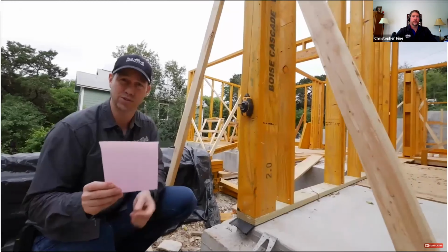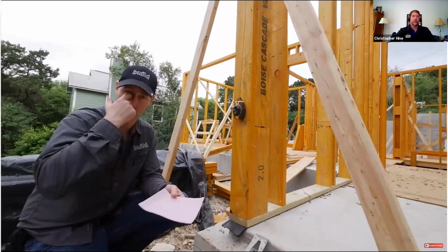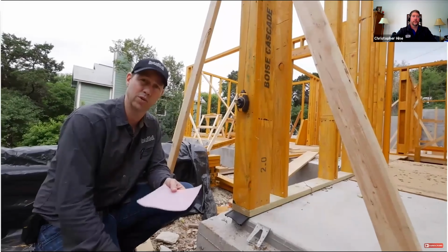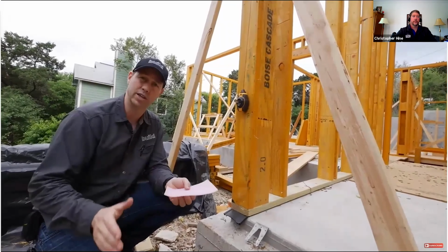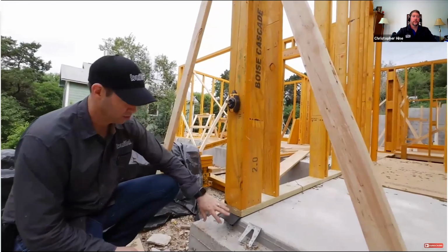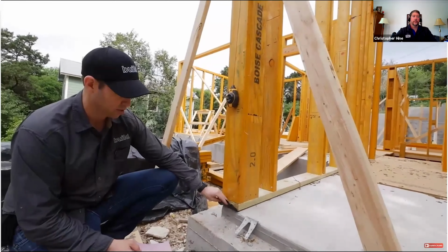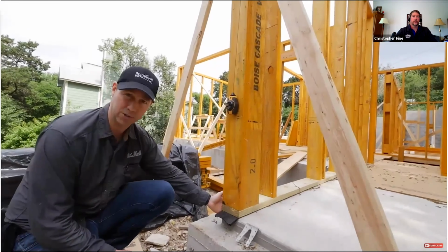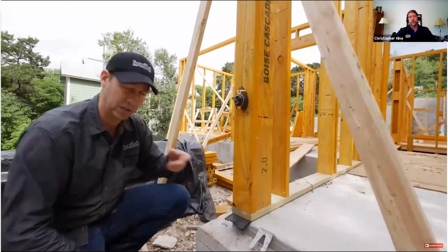I've built a lot of houses with this, but this is a belt and suspenders approach. As I've tried to really tighten down the air sealing on my houses and the blower door scores over the years, I've found that you need to take a multi-prong approach. So this is step one, using a good sill sealer. Step two is going to be doing something to the outside as well, where your framing meets your foundation.